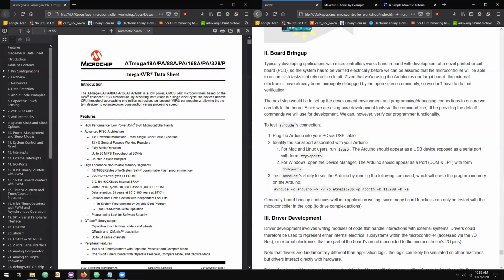So for Mac and Linux, because you guys are on a Unix system, there's this helpful command, lsusb. So if you run that via command line or terminal, then that should list all of the devices connected to your computer via USB connections. I don't know if Arduino will show up explicitly, but there should be something connected to ttyS and then a port number.